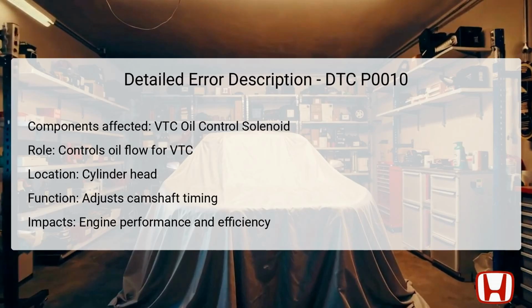or increased fuel consumption. When diagnosing DTC P0010, technicians need to understand the role of the solenoid and identify its exact location so they can effectively troubleshoot the issue. With this understanding, they can follow the diagnostic procedures to pinpoint the failure accurately.